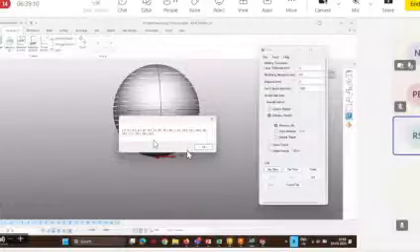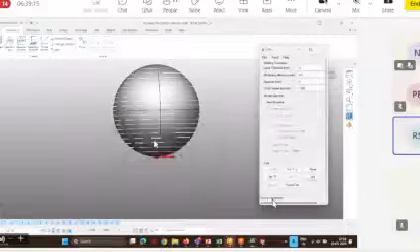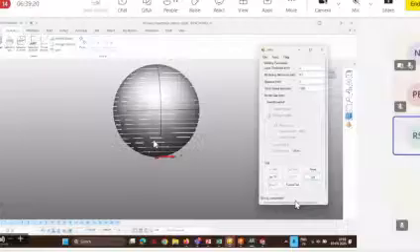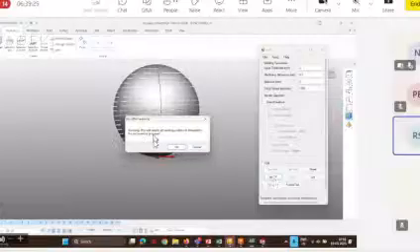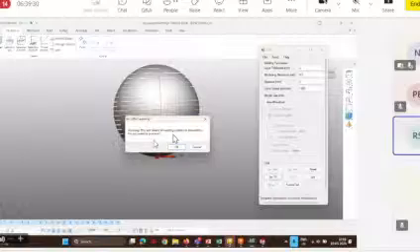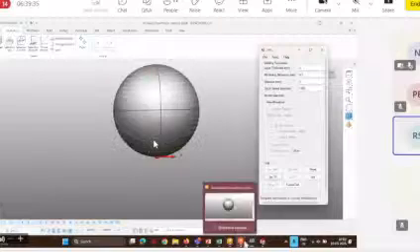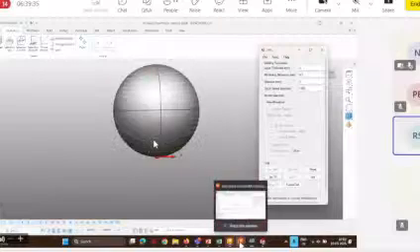So now it shows that slicing is already done. I click OK. You can see slicing is completed. Next step is I need to generate the toolpath. For that, I just need to click on this 3-axis toolpath. Just click 3-axis. It will give one alarm that all the entities already open in PowerMill will be deleted. Just click OK.